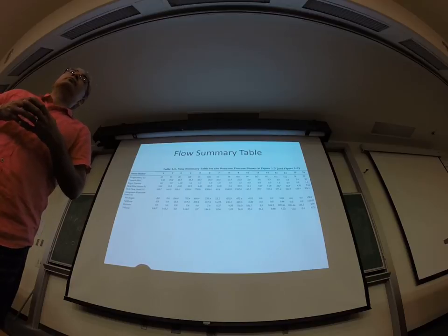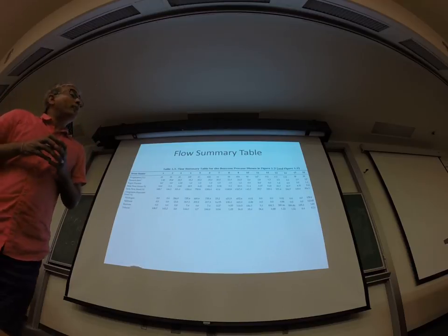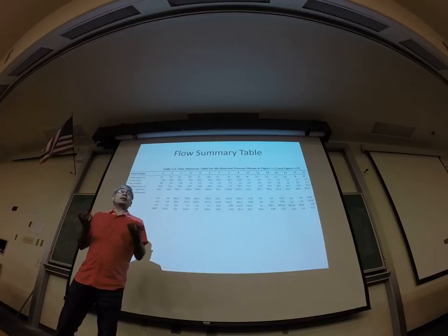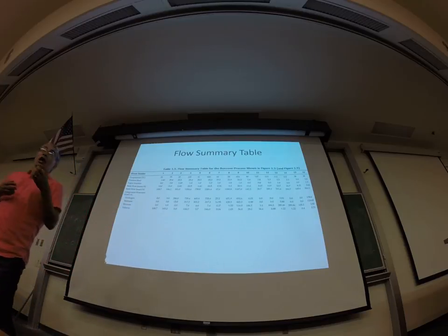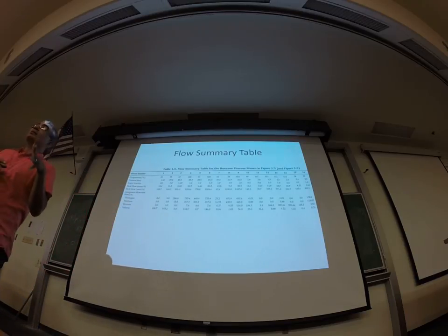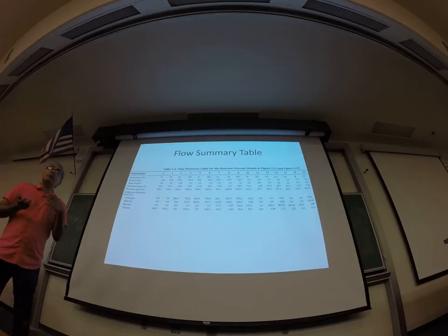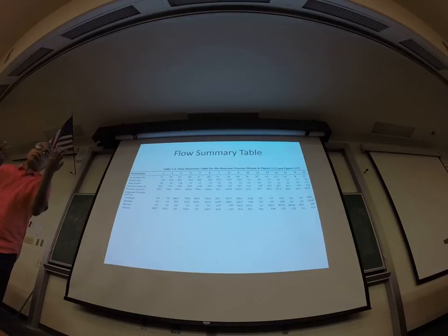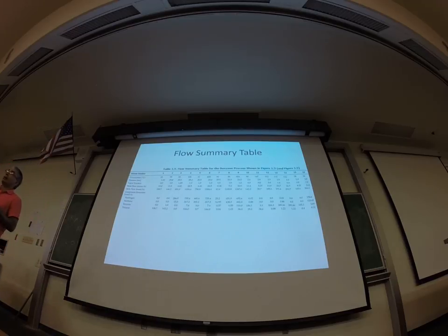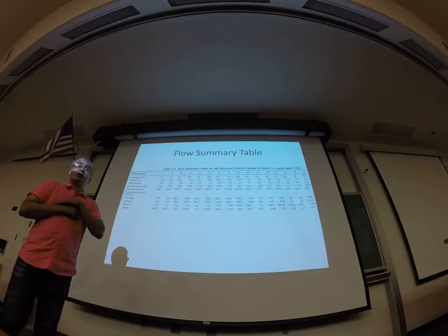Yeah, you scale up benchtop experiments. So basically, yeah, you have to model the reactor, right? A lot of other streams are easy, like heat exchanger is easy. Those can be determined just from mass balances, but after the reactor stream, you have to model the reactor. And somebody was asking last time about scale up, because frequently if you make predictions on a reactor based on benchtop data, you have to be very, very careful, because scale up is not trivial.